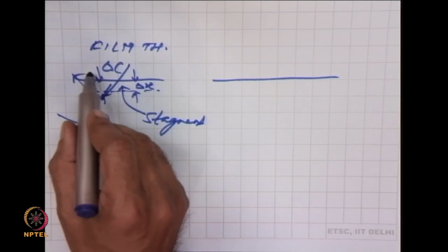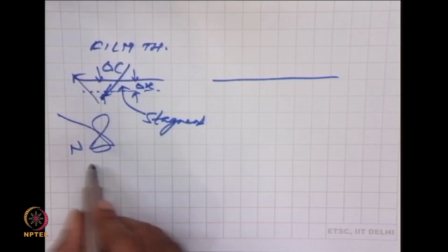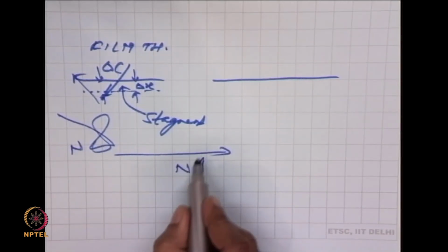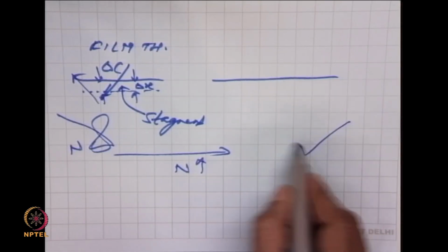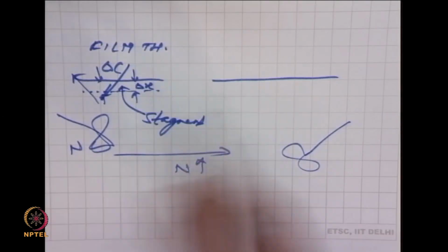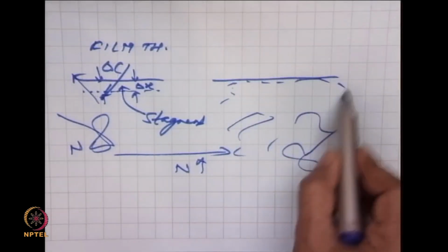As opposed to this, supposing that we increase the stirring way too much, we create too rapid mixing over here, then we might have an extreme situation where the turbulence created here could reach right up to the surface.